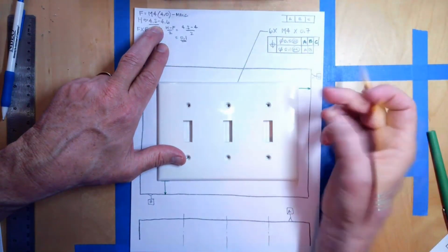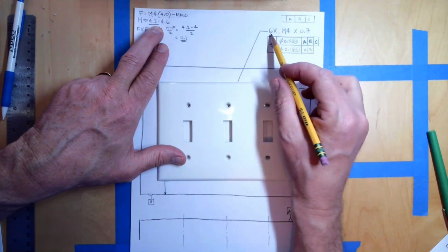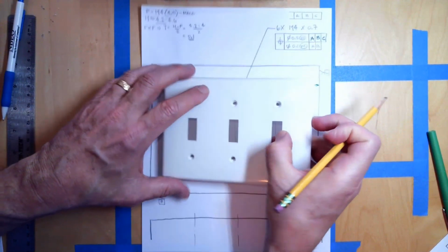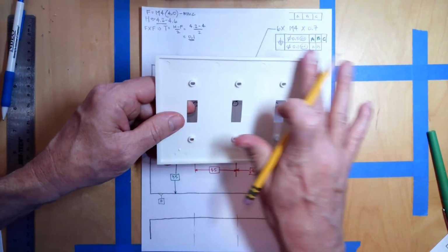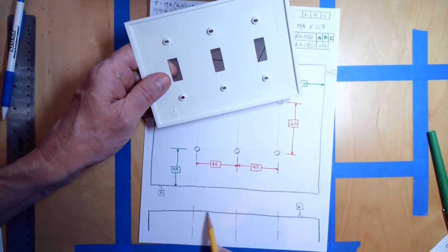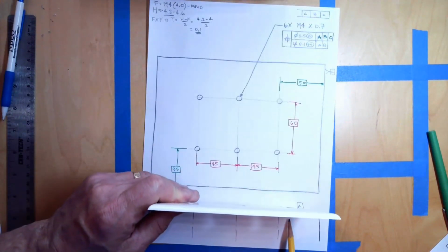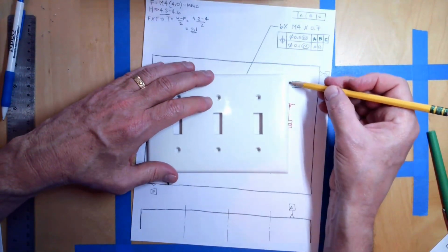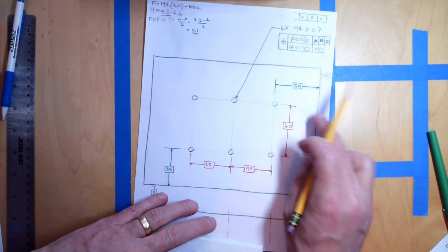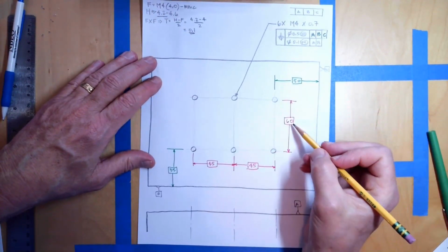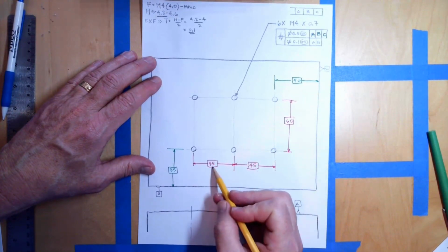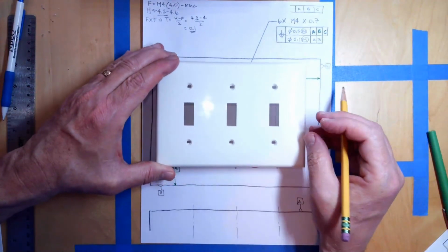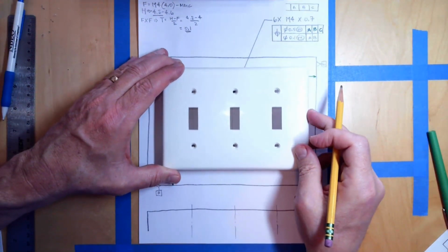This composite positional tolerance would be exactly repeated for this. A would become the bottom surface here because that's the mating surface for A down here. This side would be B, and this side would be C. This 60 and this 45 and this 45 would also be exactly repeated in the drawing of my outlet cover.